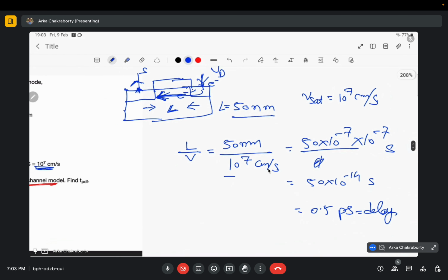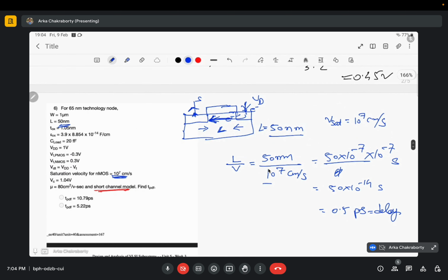What we are talking about when we are discussing electronic circuits is capacitive delay. That is the time taken by the current to charge any capacitance. It might be load capacitance, it might be parasitic capacitances. So it is always charging or discharging delay. Even in diodes, the delay, that recombination time and everything we can describe in terms of capacitances.